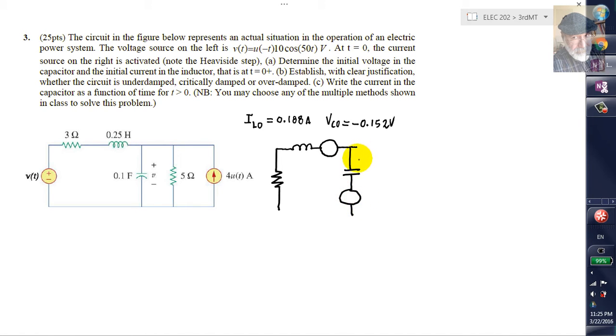And you're asking yourselves, hey, what are you doing there? Why are you drawing some new sources in the circuit? Well, those sources, if you remember, are the initial condition sources of the inductor, the one on the top, and of the capacitor, the one in the middle. What are the values of those elements? This is for t after 0.